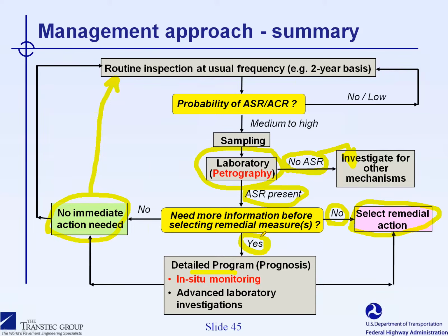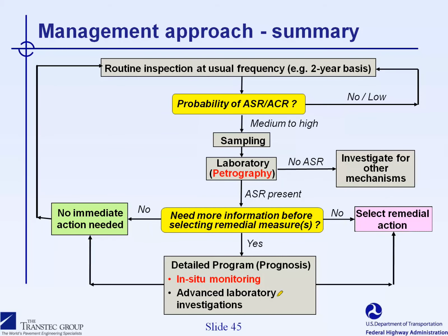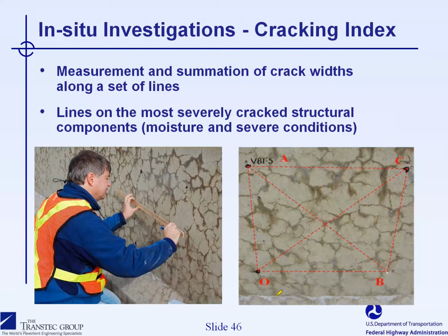But if there is a need to do some further testing and evaluation, because the concrete structure is a fairly large structure and the engineers might need more information about the extent of ASR in the concrete, then there's a possibility of doing a detailed evaluation program to evaluate the prognosis, so the potential for future expansion, either by in situ monitoring or advanced laboratory investigation. So in situ monitoring will be one of the interesting steps. For example, one